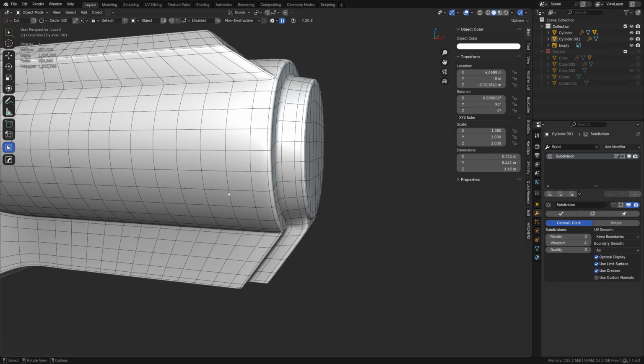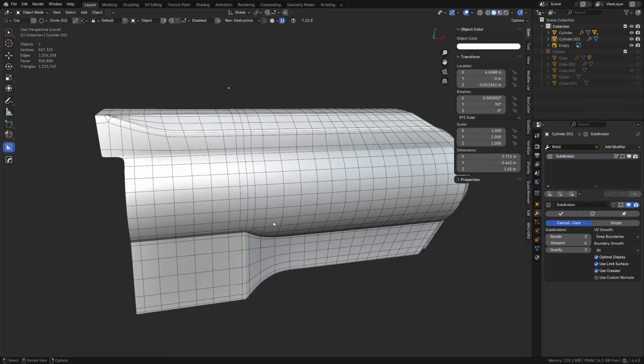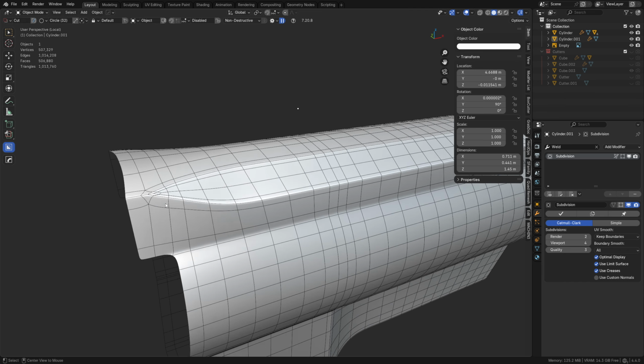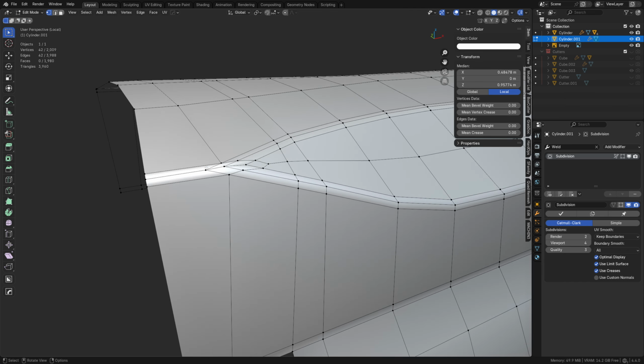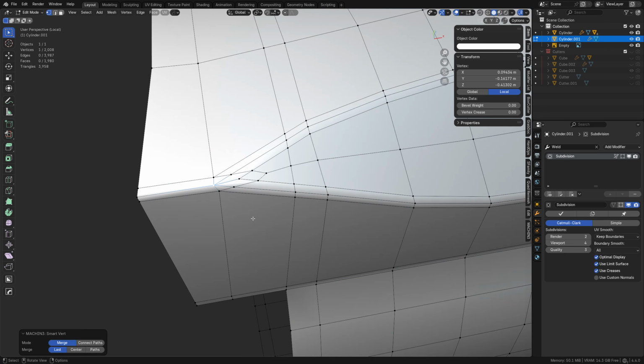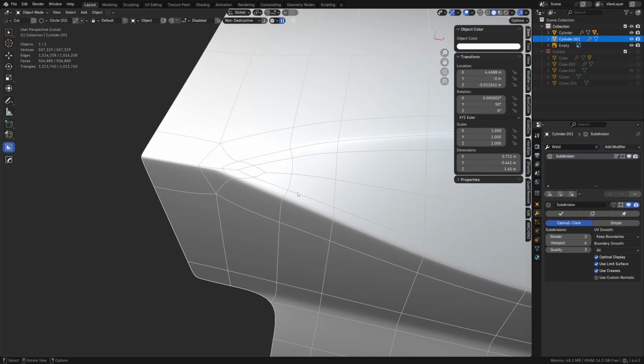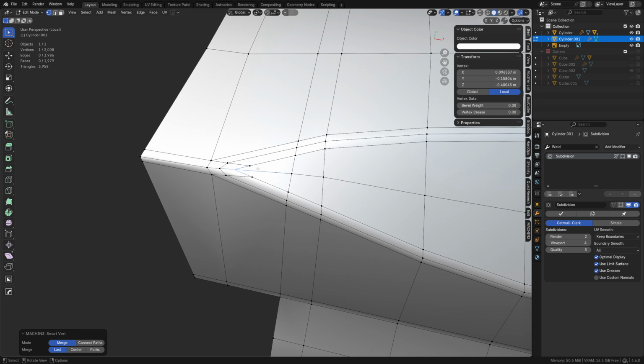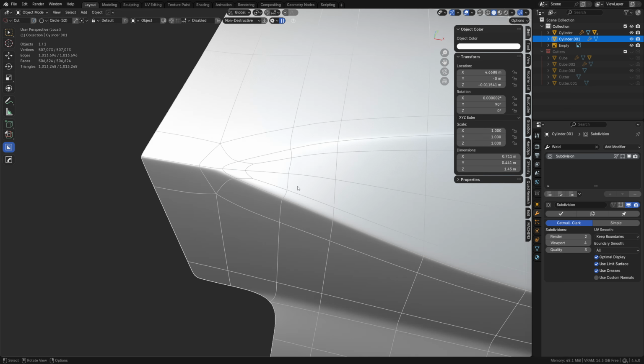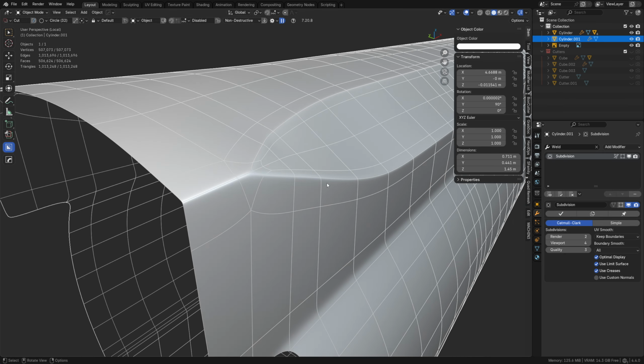And that's quad modeling, guys, subdivision modeling. It pretty much goes something like this anyways. As you're learning it, you're not probably going to do it super fast, and sometimes you'll make mistakes or errors. That doesn't need to exist. We can work that back out. It's kind of a weird topo in this area. Don't really need all of that like that. Maybe a couple quads here. And personally I like to use two quads like this back to back because it creates a half inset. So that's something worth knowing, I think.